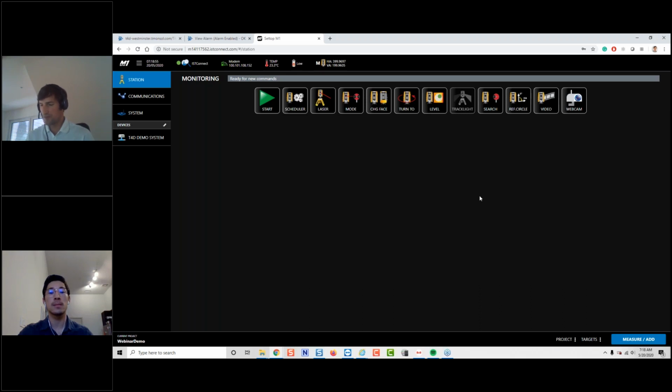A very similar question. Maybe it's a combination of the previous 2 questions. Is it possible to link T4D to a network of GNSS receivers to study the displacements of a city in 3D? It's a question from Youssef. So yes, it's pretty similar to what I've just described with total stations. You can also add multiple GNSS receivers, and we have real-time GNSS engines in T4D and also post-processing engines. And so yes, you can connect all of them, and you also get the displacements in 3D, the height component, for example. I mean, there are different settings, baseline mode, VRS mode, but this is too detailed now. So the short answer is yes, this is supported.